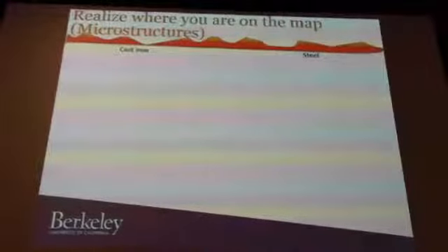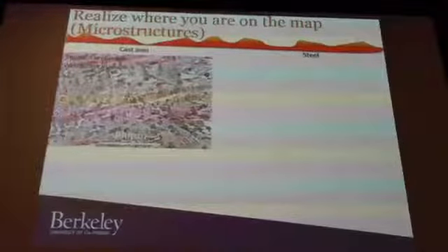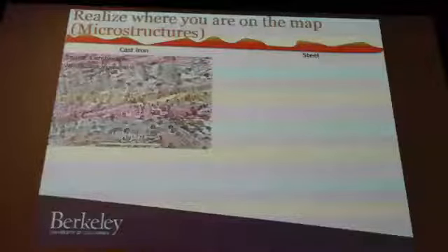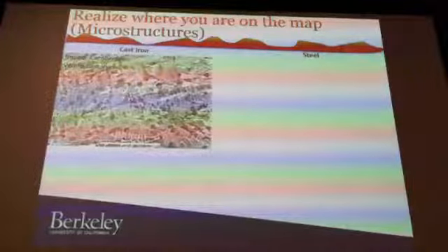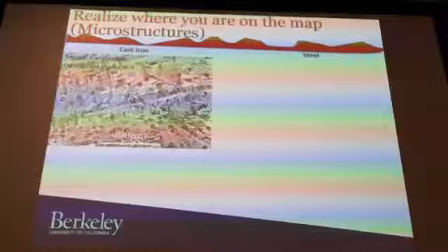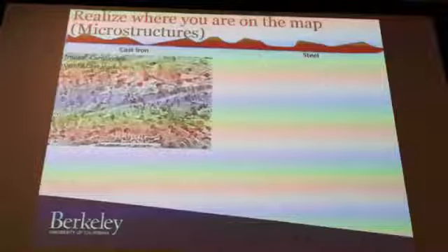So when we look at the microstructures of our product from steel making as a cast iron, this is what it looks like. It's called ledeburite, and looks pretty like a screensaver kind of. But we can see sort of a cross section of our Christmas tree, which we call dendrites. The white stuff is cementite, and the brown stuff is pearlite, and so that's the white cast iron as it comes out of the blast furnace.